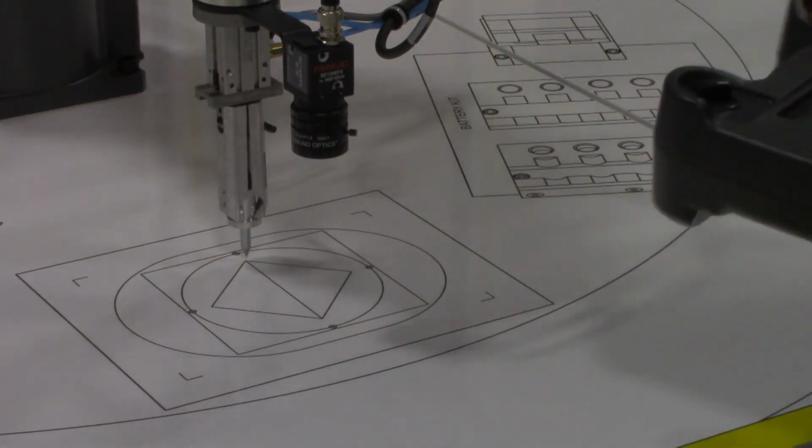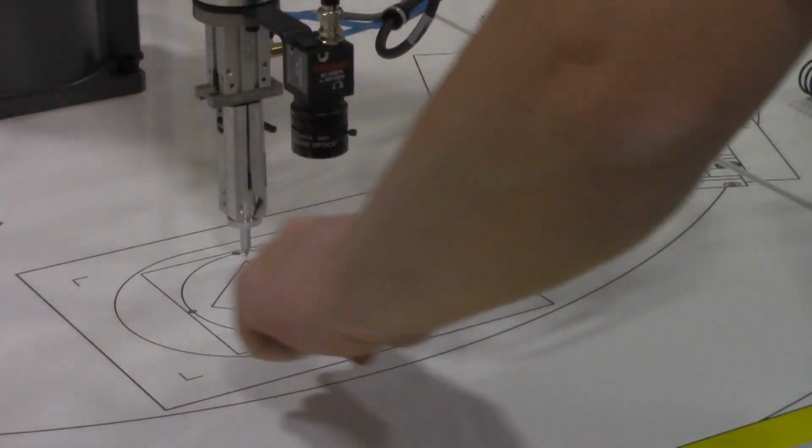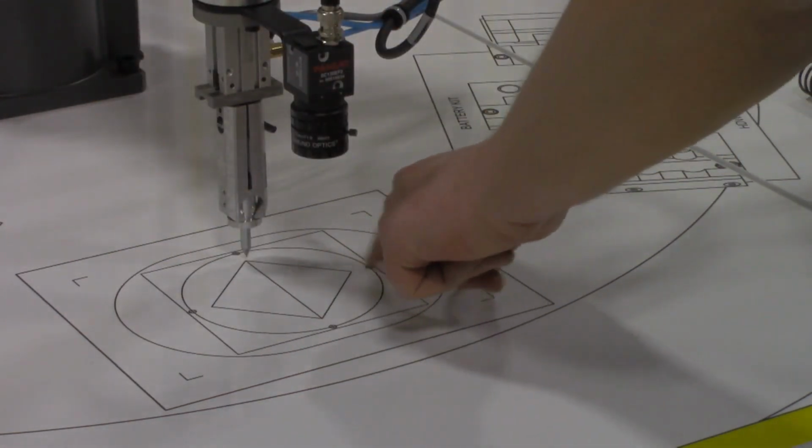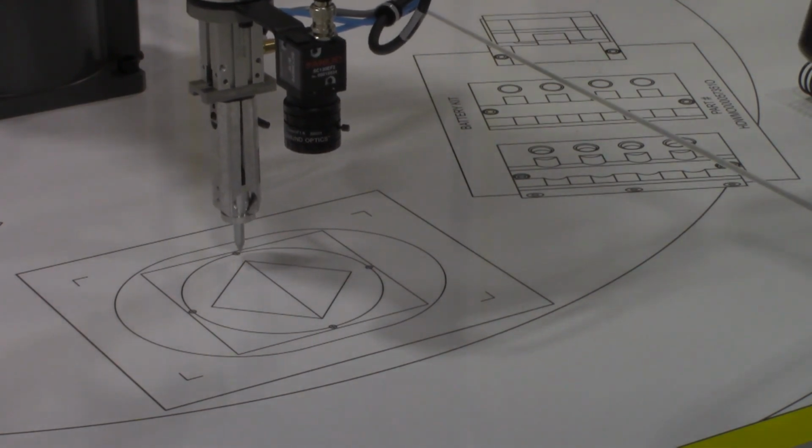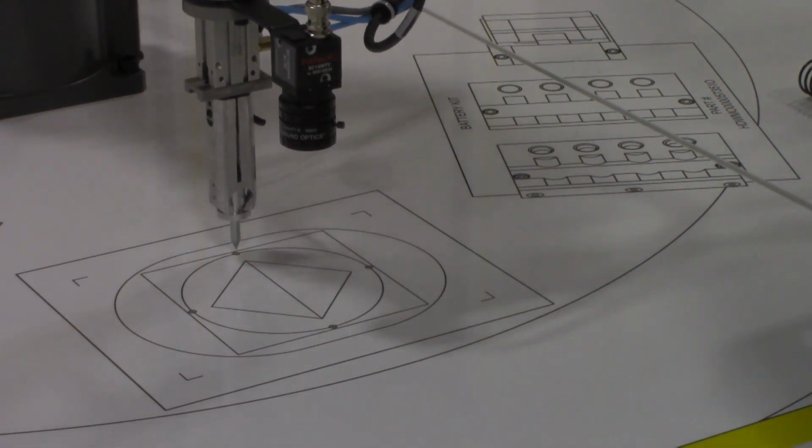So we're going to record these 4 points that have the little center marks on them, and then we'll update those so that we can run them separately, or as an arc. Okay, so the first thing is just to record them as regular points, as regular linear, and then we'll get into the menu and update them. So I'm going to move back here. Looks like that's the next point, so I'm just going to hit Shift Record.